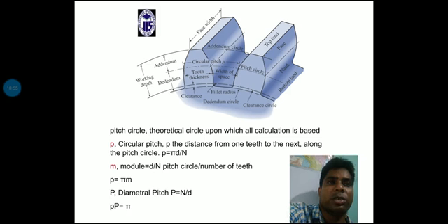That tangent is the connecting tangent, and it has some gap, because if no gap is allowed, the two teeth profiles are totally compacted, and if the two teeth are connected, we cannot separate them. That's why we give some clearance to split the two gears when the engagement is over. That is the mechanism of law of gearing.